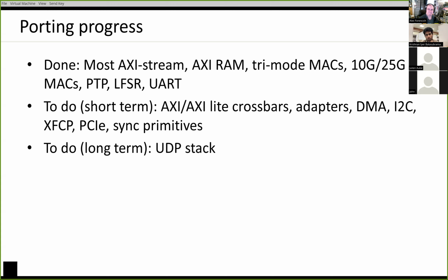There was a change I had to make to the LFSR module that significantly improved things. I did an overhaul of the LFSR module. Previously, with the Verilog version, I didn't have it written in a very efficient way, and as a result it was generating a very, very large amount of C++ code when you run it through Verilator.